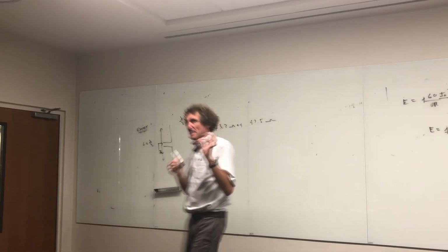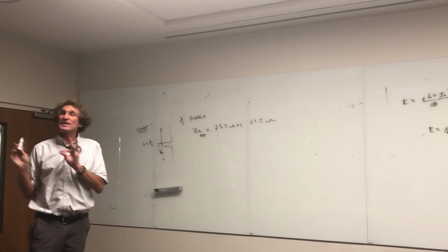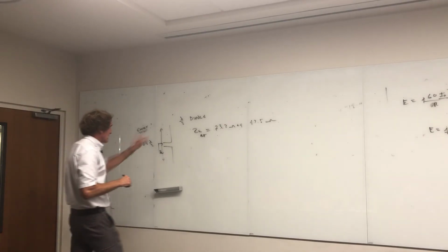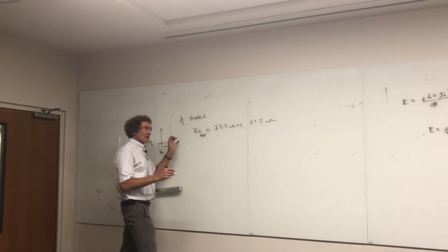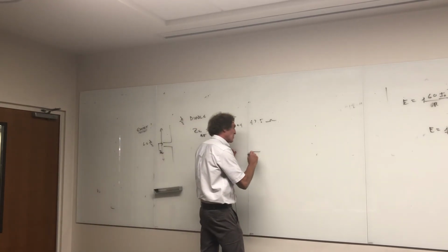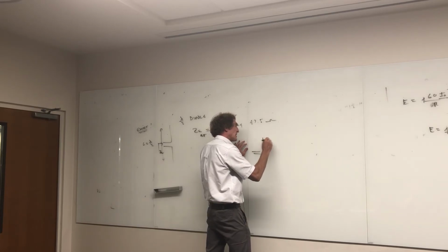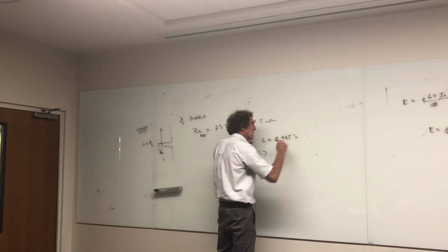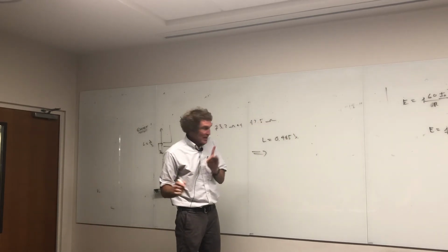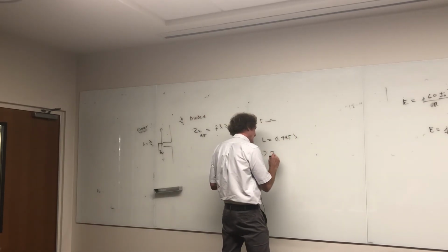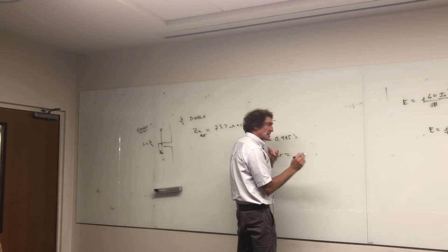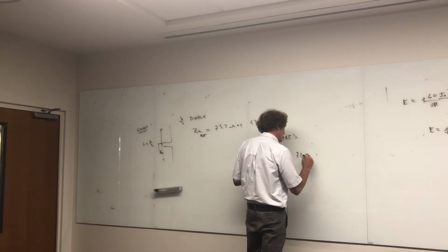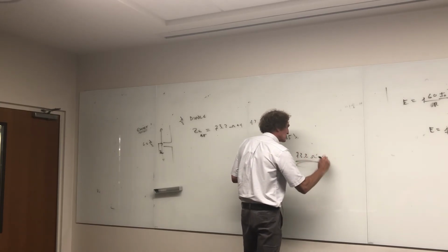But if you can take that antenna, this is real important, and trim it down, instead of being λ/2 or 0.5, if you shorten it so the length goes to about 0.485 λ, and I'll tell you how you do it, then you get a Z input impedance that is just this part, 73.2 ohms plus j0.